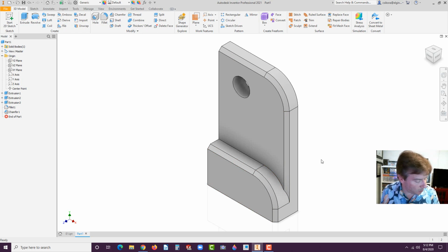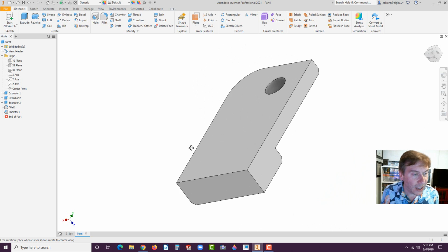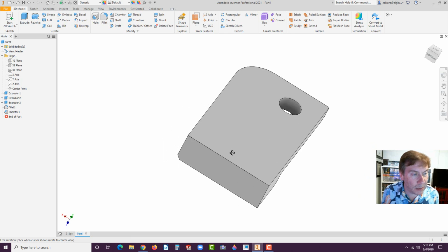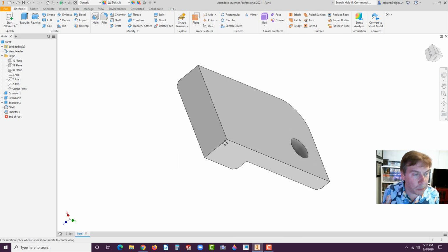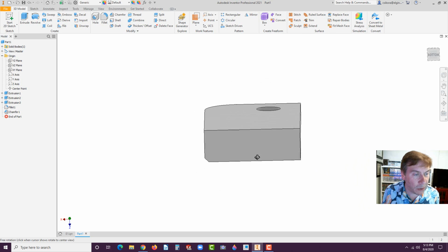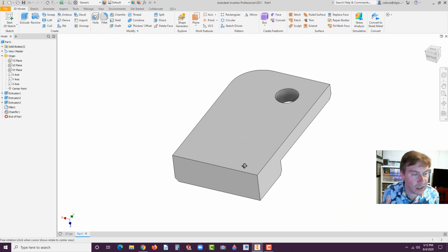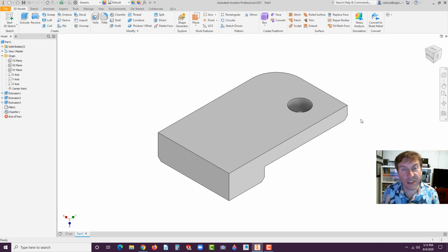Okay, let's hold Shift and your wheel, move your mouse left until you rotate it like that. Now notice sometimes little circular motions could help you position it either forward or backwards, clockwise or counterclockwise. And so let's say you wanted to get this back corner, and there really wasn't much of an option there. We could click on this back, bottom, and left, center. And that gives us a nice little back area there. So if you wanted exactly like mine, feel free to do that on that little box there. Click on that corner. And it gives us an isometric view from that perspective.